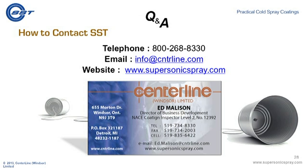There is no cure for cold spray coatings. We don't have to wait for any chemical reaction, and we don't have to wait for any thermal cooling or reactions at all. The moment you're finished cold spraying is the moment that you can finish the part, or if you're not finishing the part, the moment that the cold spray process is finished, your part is ready to go.